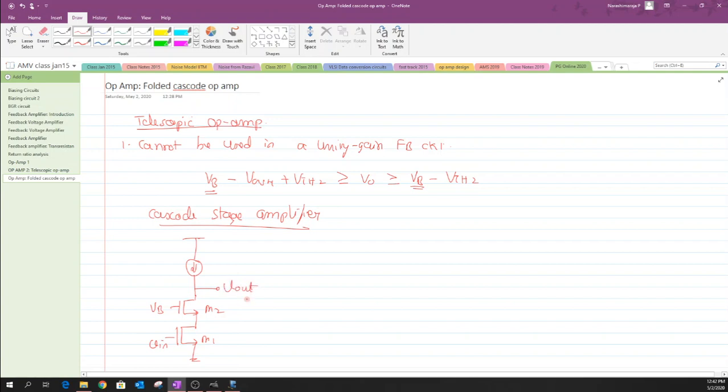So this is the configuration that we had, and in this configuration we found that the value of this Vb is so much constrained. You cannot fix the value of Vb to any desired value. The fixture of the value of Vb is constrained by the DC condition at the drain of M2 as well as the DC condition at the drain of M1. So it is stacked between these two regimes where we cannot have a greater swing. This limitation happens because the cascode device as well as our input device have the same structure.